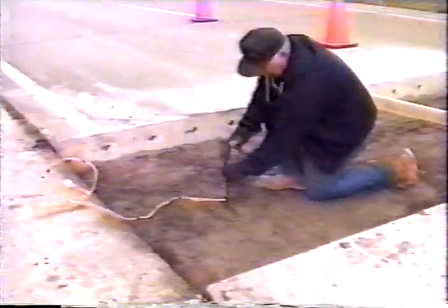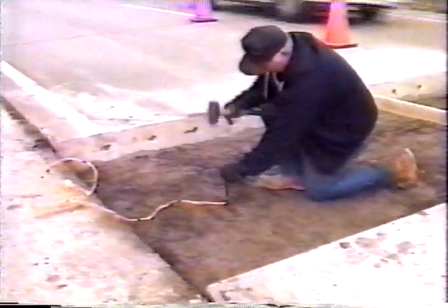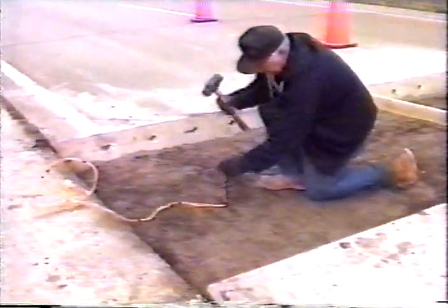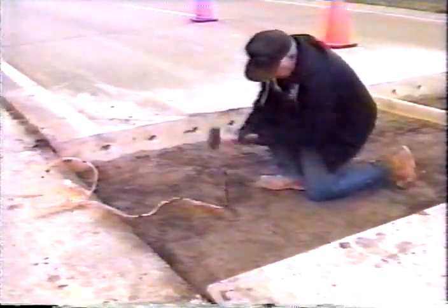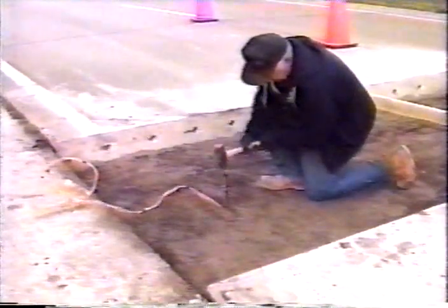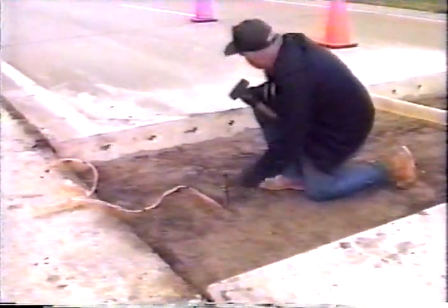For thin bonded overlays, a thermocouple is positioned within the plastic concrete, away from slab edges. For full depth construction and patches, several thermocouples may be positioned away from slab edges at different elevations. Usually the thermocouple wires are attached to a tree that is driven into the subbase so that the thermocouples are properly positioned prior to concrete placement.